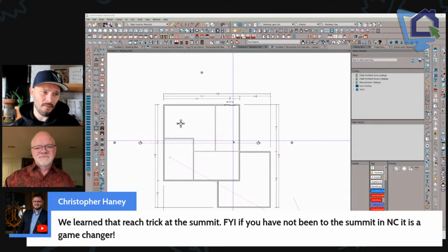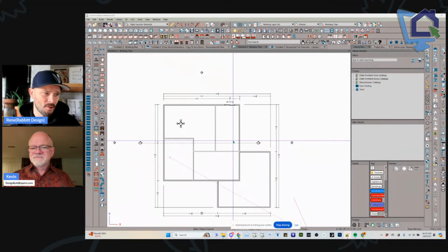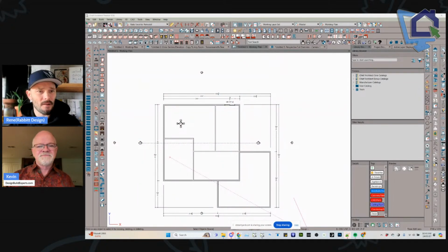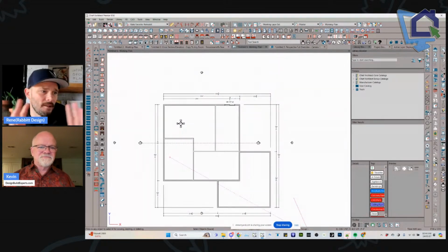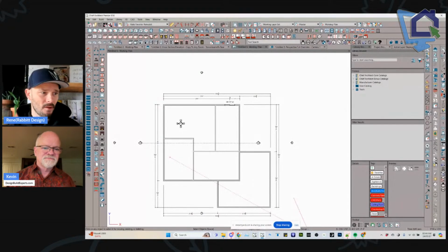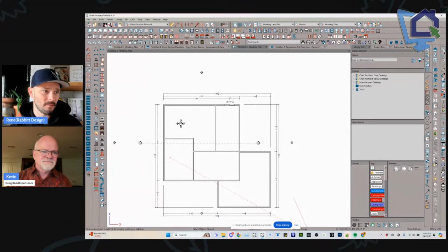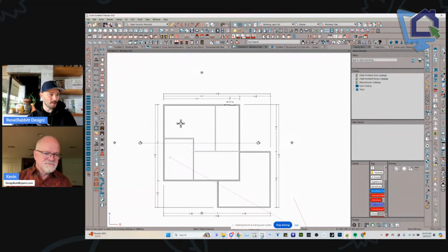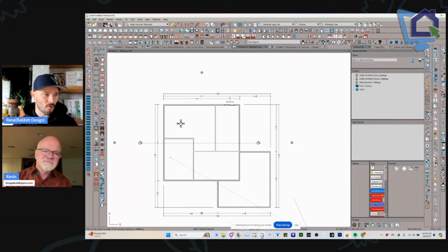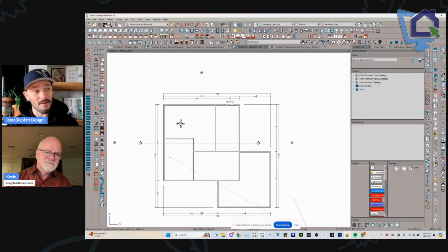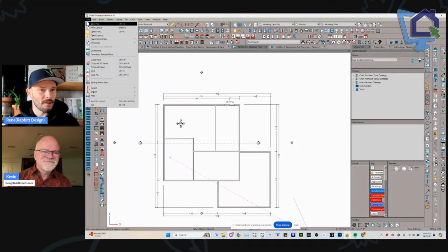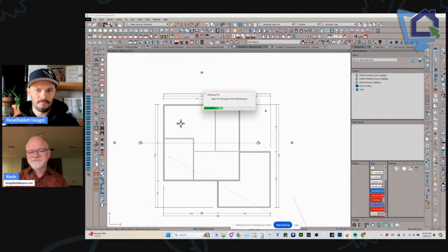And one of the things that they gave us was XY position in layout and XY position in plan. What that allows us to do is some automatic callouts based on where something is on your sheet. I'm driving all my callouts for all my details based on where that detail is on my sheet. So it's automatically numbering things for me and updating without me ever having to type. I could show that really quickly. Yeah, that's pretty incredible.